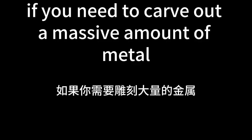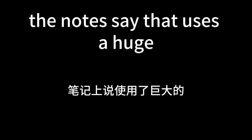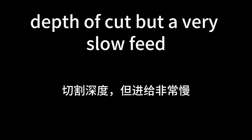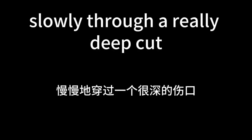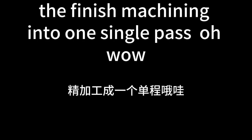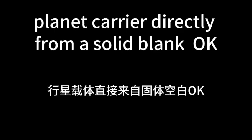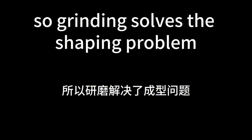But if you need to carve out a massive amount of metal, engineers use creep feed grinding. Wait, the notes say that uses a huge depth of cut, but a very slow feed? Why go so slow? Because by moving the tool very slowly through a really deep cut, you actually combine the rough machining and the finish machining into one single pass. Oh, wow. So it is perfect for carving out deep slots in a planet carrier directly from a solid blank.